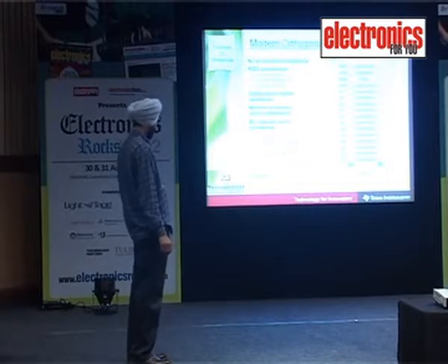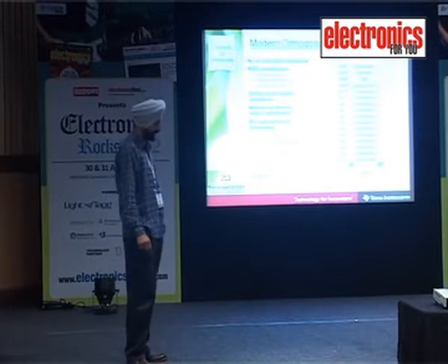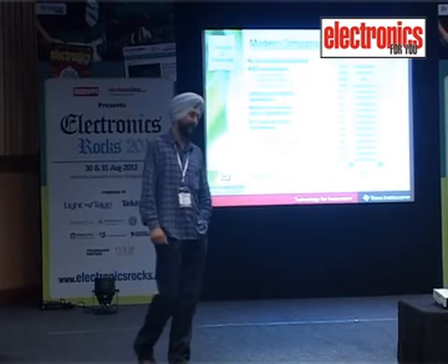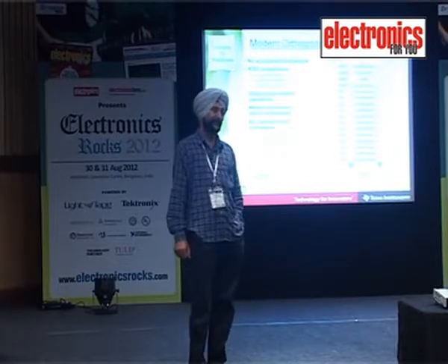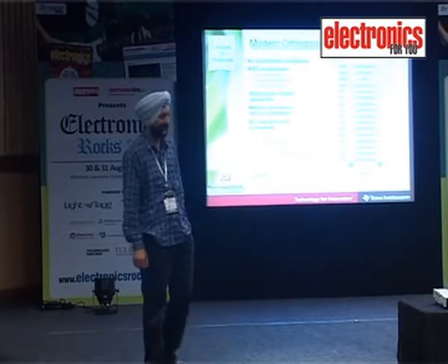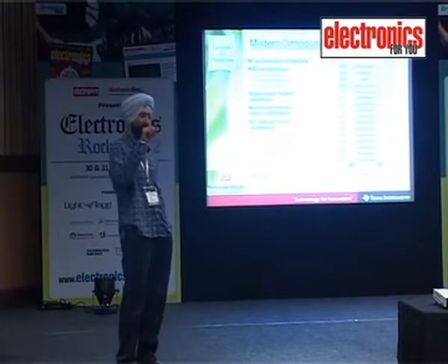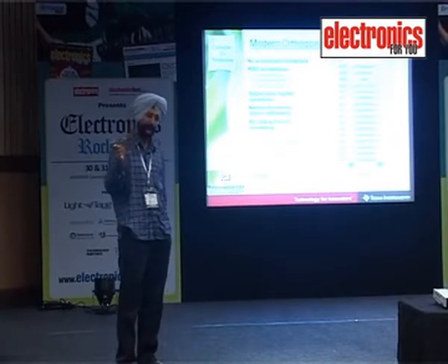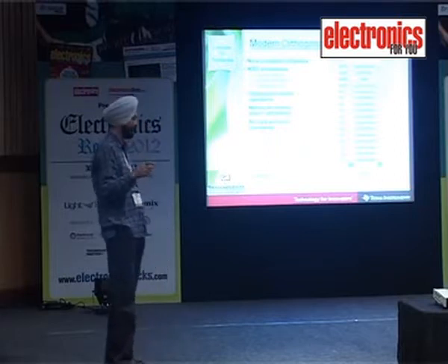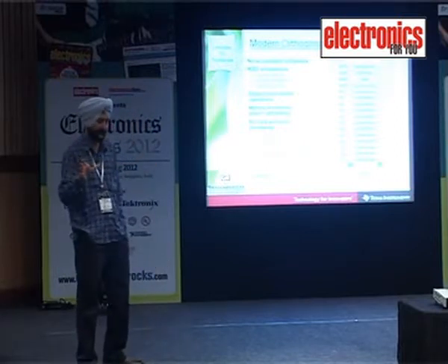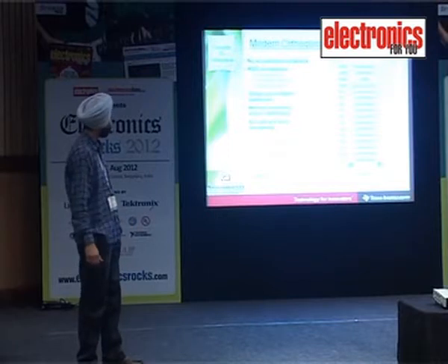Then we have the constant generator, which is internally used by the CPU. And R4 to R15, we have a complete 12 working registers. All these registers are 16-bit registers, but if it is needed, we can use them as 8-bit registers. You can use move.b. So it means you will be able to access only the lower 8 bits. But if it is needed, you can use them as 16-bit registers also.